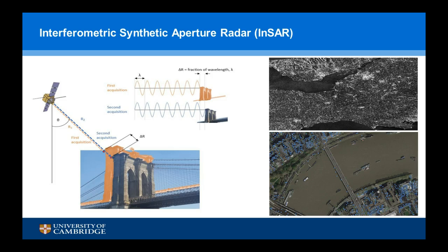Then what you do is you take a series of these single SAR images, and you pass them through an image processing technique. There's a couple of different types of techniques, but what was used in this particular study was something called persistent scatter interferometry. Persistent scatter interferometry, or PSI, makes use of objects that reflect very well. So we take objects, for example these bright spots that have a very strong coherence or strong reflectance, and we monitor those specific points over time and discard any of the less stable points.